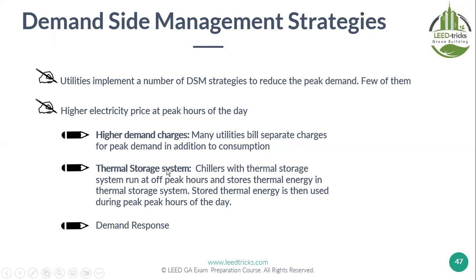Thermal storage: of course, at night there is no demand on power, but the power is there. So why not store it? Chillers with a thermal storage system run at off-peak hours and store thermal energy, and then use it during the peak hours.